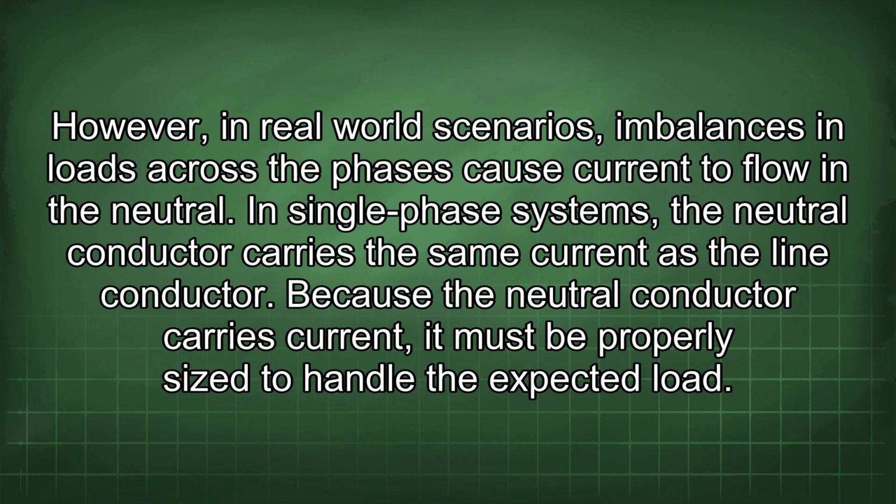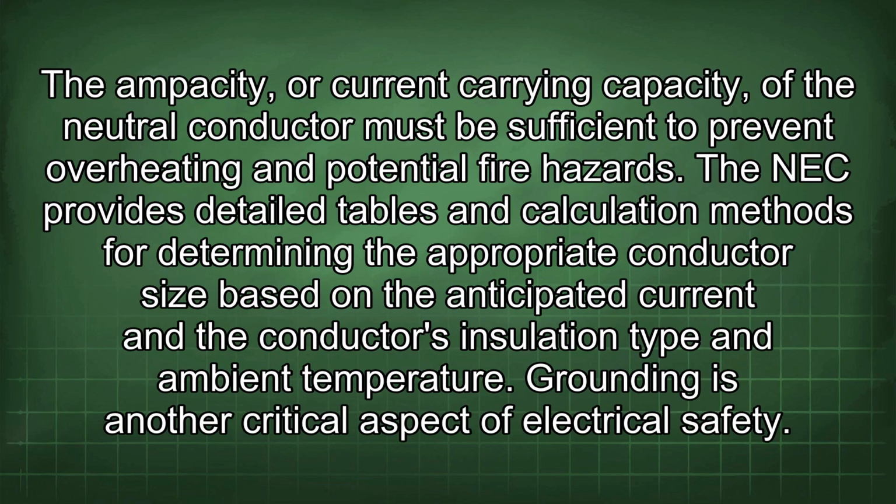Because the neutral conductor carries current, it must be properly sized to handle the expected load. The ampacity, or current carrying capacity, of the neutral conductor must be sufficient to prevent overheating and potential fire hazards. The NEC provides detailed tables and calculation methods for determining the appropriate conductor size based on the anticipated current and the conductor's insulation type and ambient temperature.